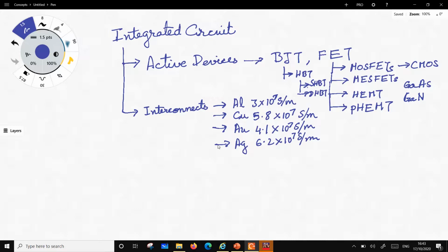We know that if we consider a cross section of a conductor, let's say this is a conductor, a wire, then most of the currents would reside on the surface, up to the skin depth. So the center of the conductor will not have any current flowing at microwave frequencies. So if the conduction of current is on the surface, it has to be a fine finish. And that's what the gold does, right?